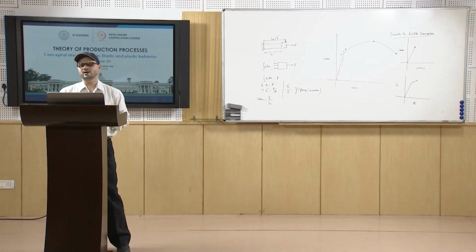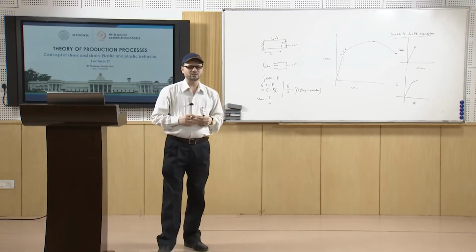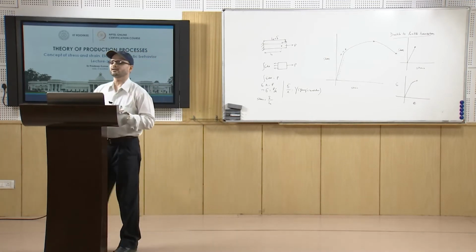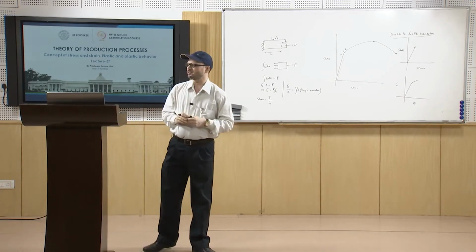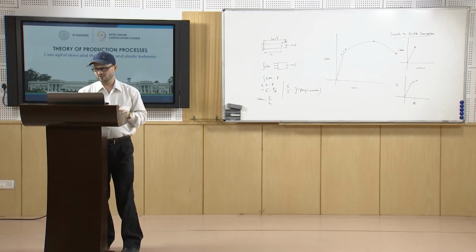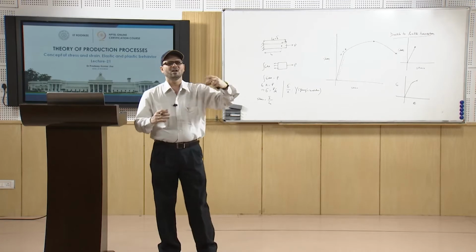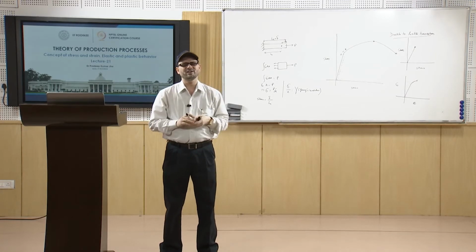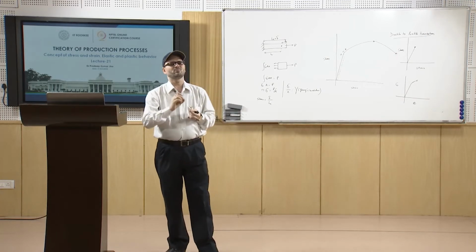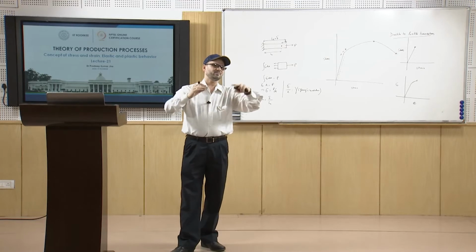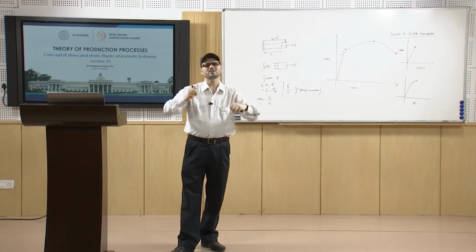Then you also have fracture. You may have sudden brittle fracture, you may have fatigue, which is a progressive fracture, and then you have delayed fracture. You may have sudden fracture, which we have seen in purely brittle kind of material, where they don't give you any kind of indication. You have a formation of a small crack that propagates, and ultimately the area becomes so small and the stress level increases so high that the material fails there.